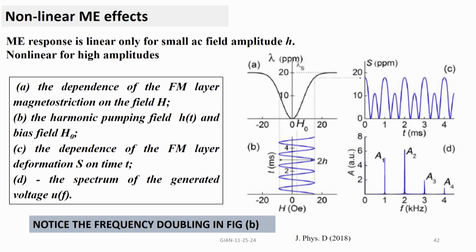That means the positive amplitude is somewhat higher than negative amplitude. That's what you see in the response. But the frequency is doubled. See that? Because in one cycle here, there are two peaks. So it's doubling of the frequency. That's nonlinear effect. And you can put together a composite based on this frequency doubling circuit.